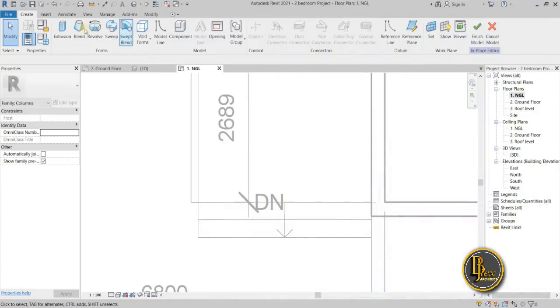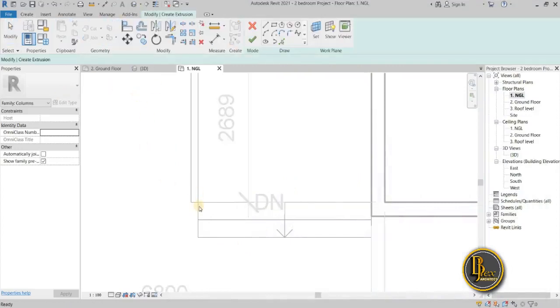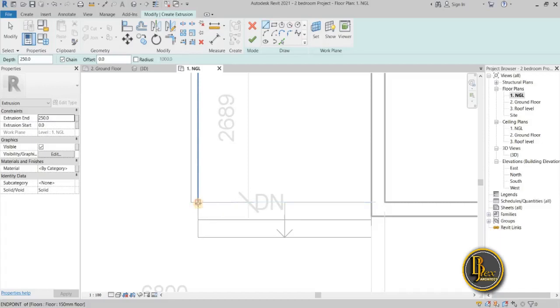In order to create that, let's go to our extrusion tool. In our extrusion, we'll be drawing it on our ground floor level. So let's use the rectangular line work, and let's create an offset for the base. Let's try 300, so that 300 on each side will be about 600. So let's try 300. Yes, all right. So let's create our column. Okay, this is our column of 300 offset each. Let's use our 600. It looks big, it looks wide, but let's just see if it works.